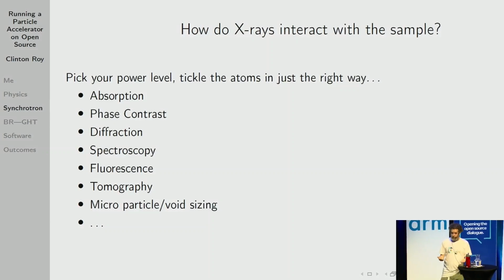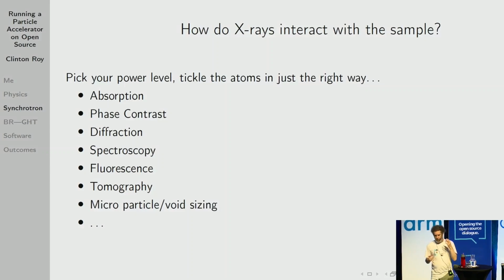Tomography, it's a medical imaging term that we do a lot of. We do a lot of techniques where we're looking inside physical things, looking for the size of particles. So for example, we can look at steel, which has an internal structure, and we can see if the steel has the same internal physical structure all the way through, or if it's got a changing physical structure. So some of the stuff we do is when a large piece of steel has fatigued, we can look at the rest of the steel using different techniques and work out why it's fatigued.